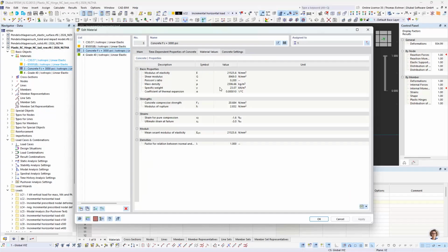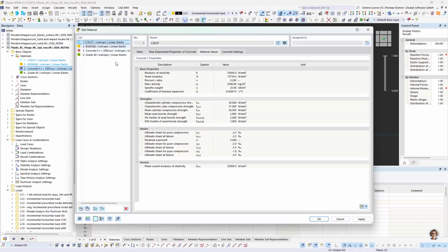So the next thing is what material value is used. We see here the material value for ACI is FC bar. We have this 20.684. You can also make it user defined and change it there. I think there's no estimated values there yet, so this value is the one that is used. For Eurocode material, that's a bit different. It's gonna use the mean value, because it's the European estimated value, kind of.